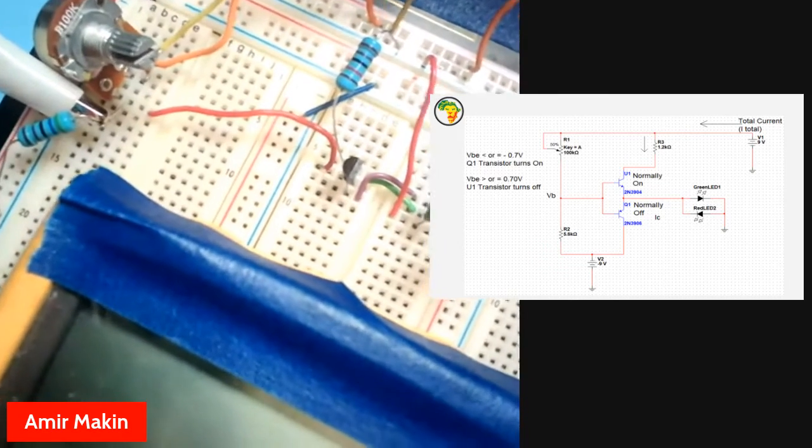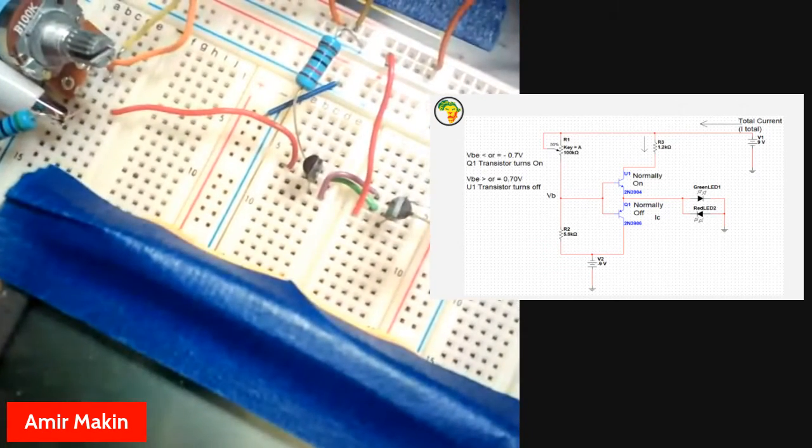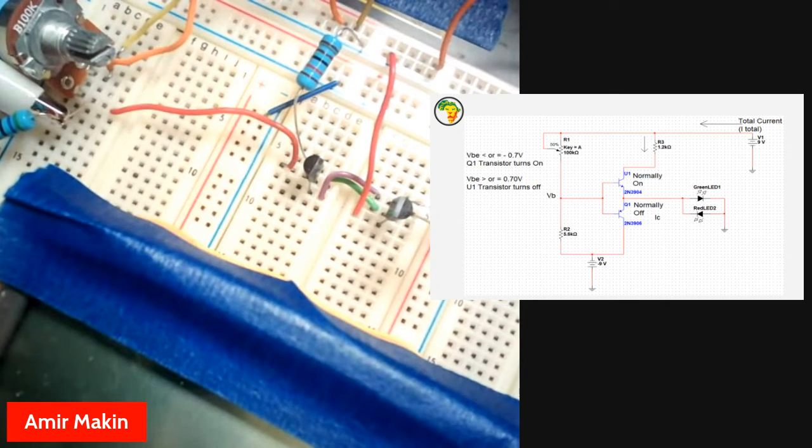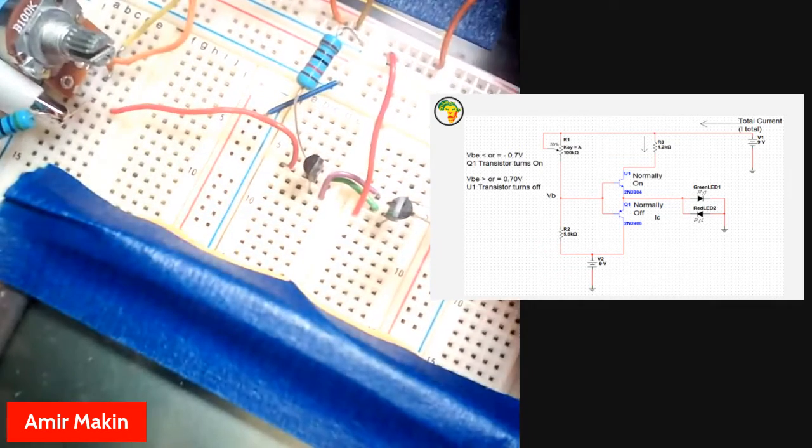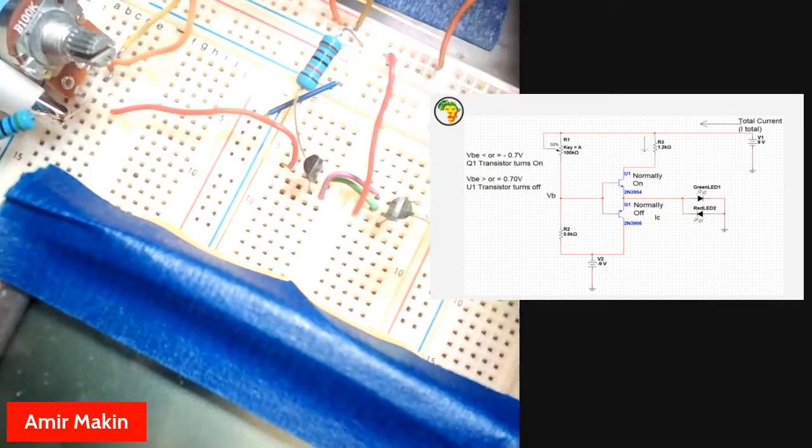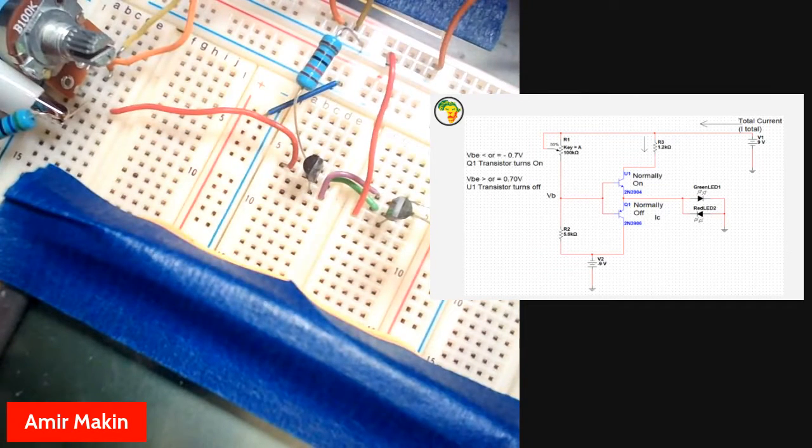The bottom of the 5600 ohm resistor, which you cannot see, let's see if I can move that right there without you losing sight of the light, is connected to minus 9 volts. Minus 9 volts is just a 9 volt battery connected backwards. That's all. Just like the regular plus 9 volts is a 9 volt battery connected in correct form, forward form, we'll say. So we're going to turn on the plus 9 volt and the minus 9 volt.